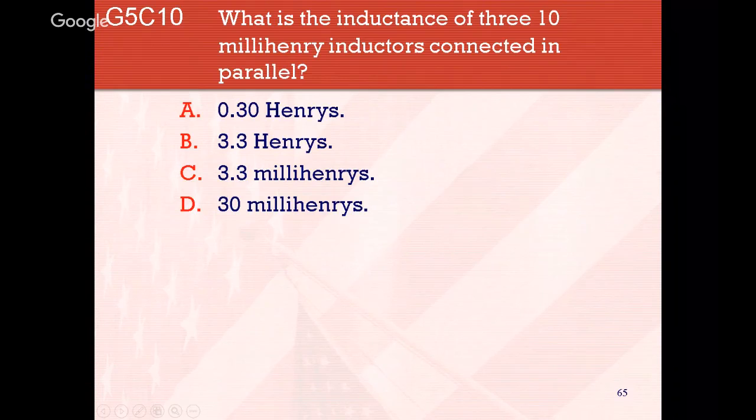But we also know that it's going to be less than the smallest value. In this case, they're all the same, but it's going to be less than 10. So the only logical answer in this is going to be 3.3 millihenries, or you're going to divide 10 by 3.